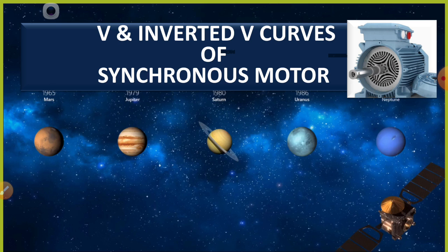That means the synchronous motor works as a synchronous condenser under no load or minimum load condition with over excitation. Now, how the armature current and the power factor change if excitation changes.